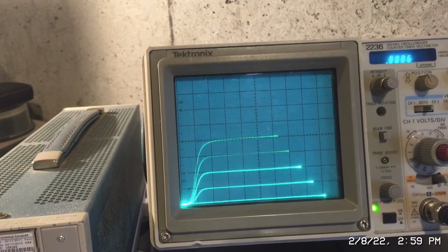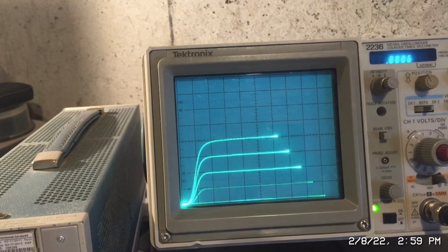Now you might ask yourself, well, what's the advantage of this? Well, let's say in certain applications like a push-pull amplifier, you want the transistors to be working together, in unison, and you want them to each be handling the load the same way. Otherwise, one's going to be a higher current, the other one's going to be a lower current, and you might see a temperature gradient between the two transistors.